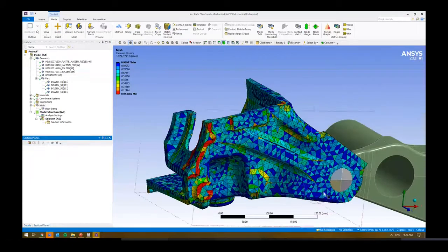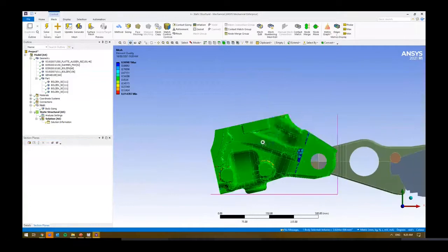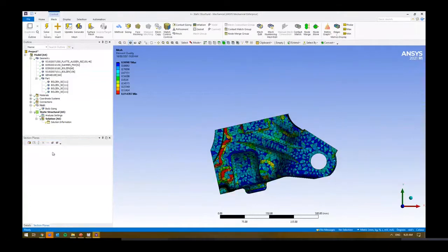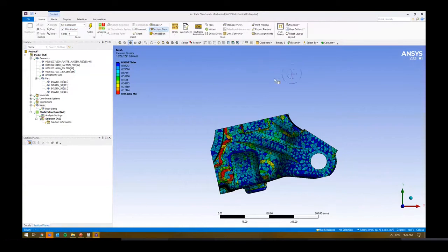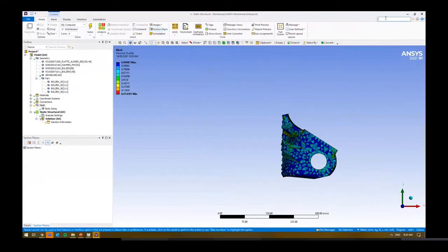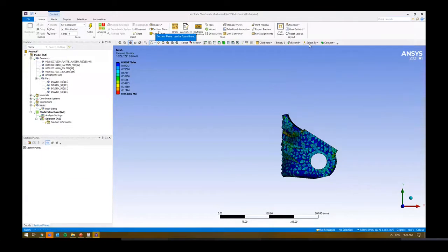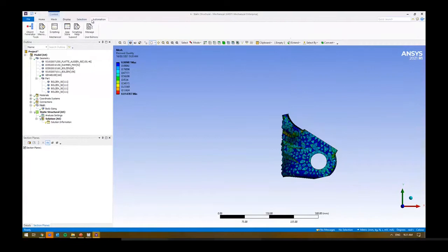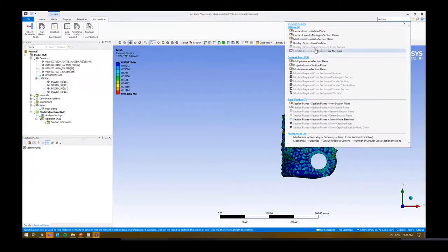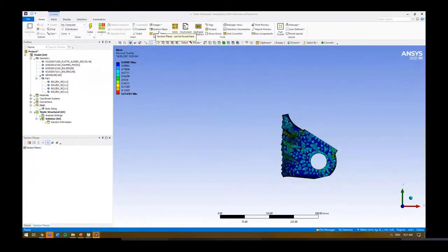And if we were to take a section, let's just hide everything else, by the way. We use this section view. If you can't find it, by the way, at the home, it's up here. Or if you always forget, at the top right, we've got a quick launch setting. Just type in section. It'll give you indication. Or if you go take me there, it'll actually go to that context. So let's go back to section. I say take me there, and it'll just indicate where exactly I need to be.